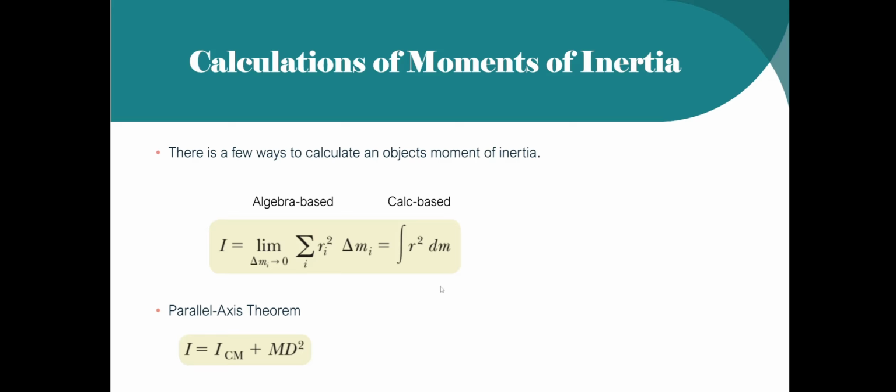I know that's an old concept to think of, but they still have things like a merry-go-round in parks. The merry-go-round, of course, is just a standard solid disc that spins around a center. That has a very easy center of mass moment of inertia. It's the disc moment of inertia, so 1/2 mr squared. You can easily calculate this one if you happen to know the mass of the disc.